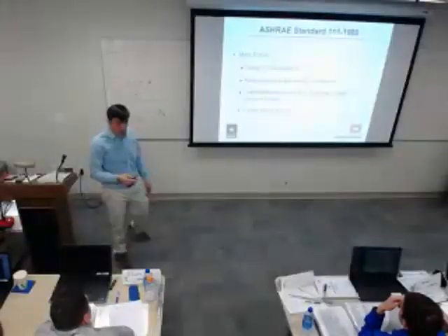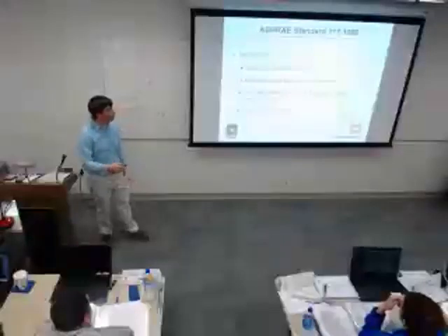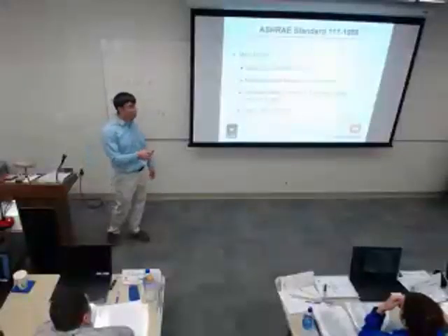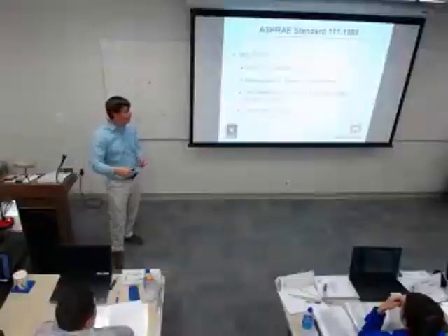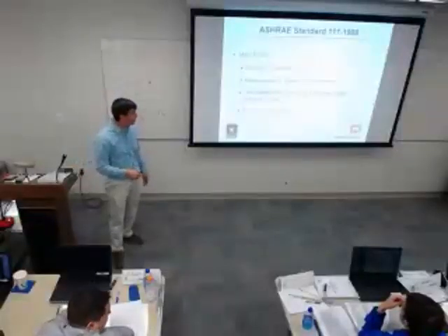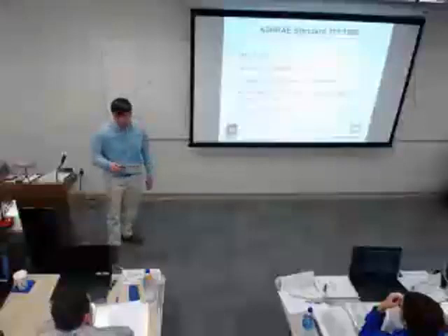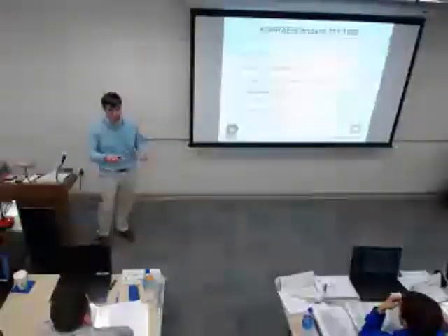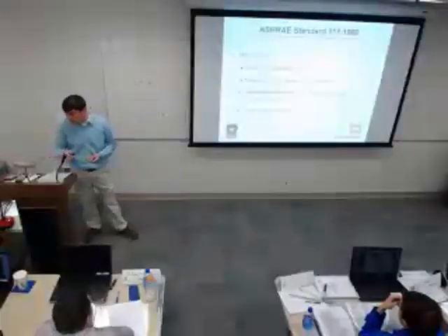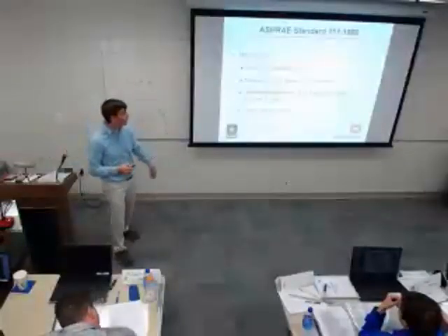This is a good document also for the design guys. It's got a lot of information on design considerations for your designs, how they might impact balancing and results in the end. It has a lot of procedures, the same things. So TAB procedures, what is the TAB guy supposed to do first when he gets on the job site? That's covered by a procedure. It's in those two books I showed you. There's other procedures in ASHRAE 111.